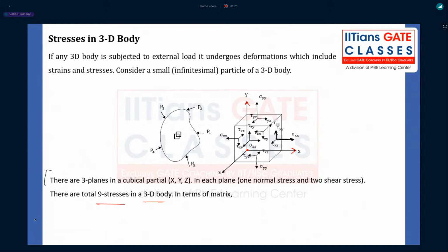Now tell me whether stress is a vector quantity or tensor quantity or scalar quantity. Because if I say velocity, that is a vector quantity. Why vector quantity? One magnitude, 5 meter per second, and you will say that it is in the positive x direction. So what you will say? 5 i cap, right? You just denote it by only one subscript. Whatever the one subscript will be there, that will be enough. You say ux, only one suffix will be required. That is a vector. One magnitude, one direction.